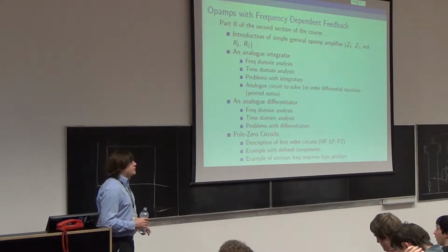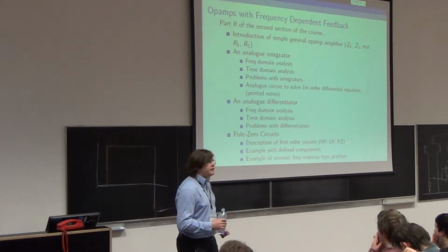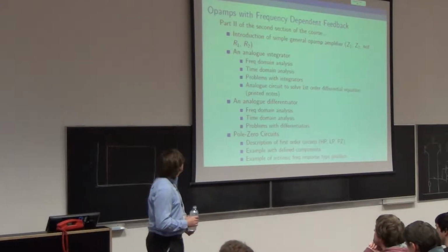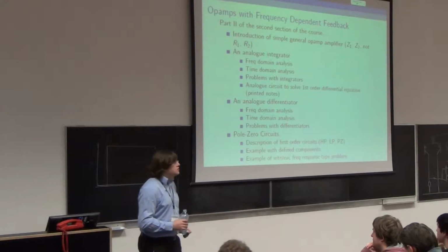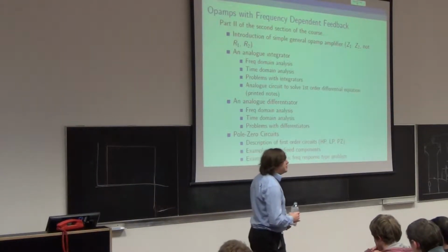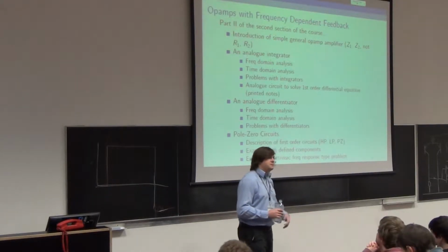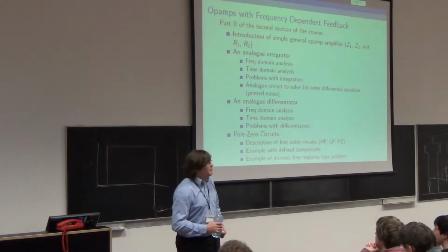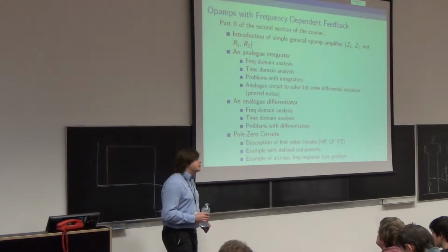So we have to go back and have a quick look at some op-amps from 118, and I'm just going to switch R for Z, and then I can talk about impedances and not resistances, and that'll make you happy. And then we talk about two circuits. It's actually pretty rare to find an integrator or a differentiator made from an op-amp. Usually you just put it into an embedded system and code it up in some programming language. But actually, they're really very useful in certain situations.